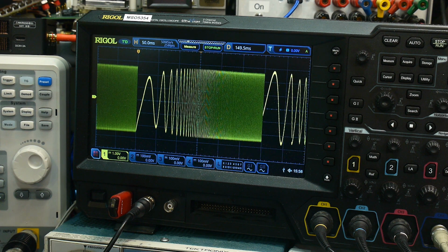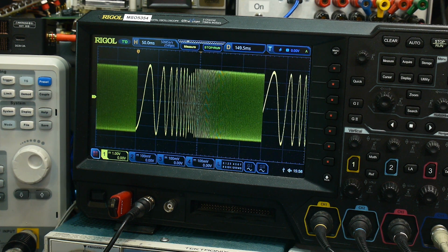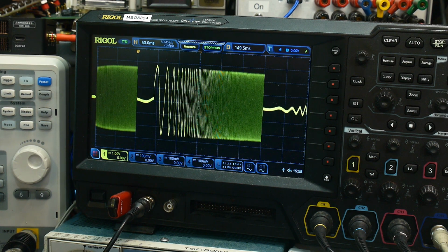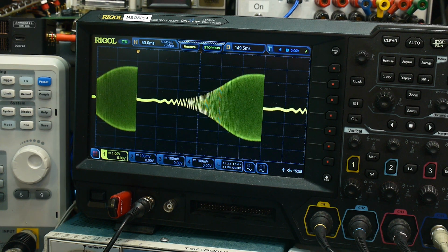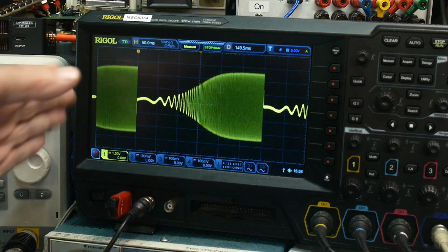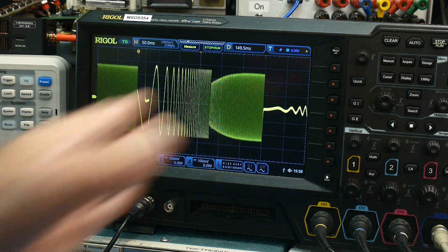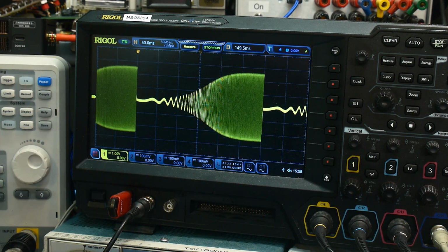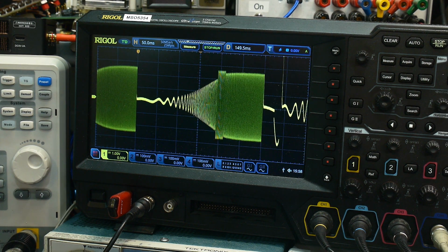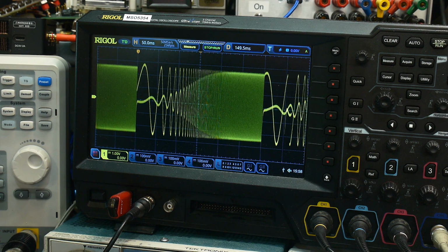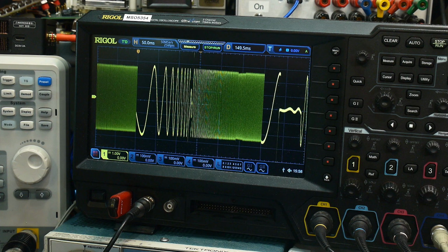So it's kind of the amplitude of this thing, and a little bit of frequency, right? It's moving. So you actually can move these things frequency-wise just by changing one resistor. So that's really nice. You can't do that with an inductor, right? And so you can sort of have a potentiometer that sets the cutoff frequency of this filter, which is super, super nice.